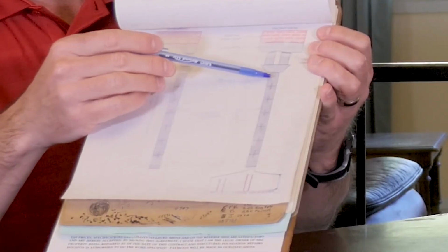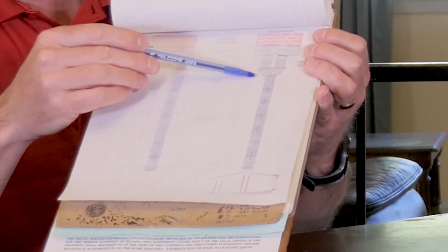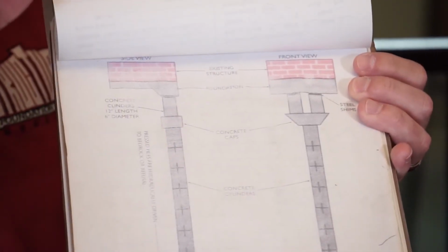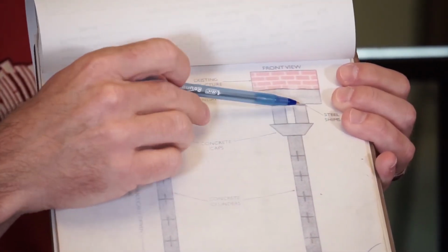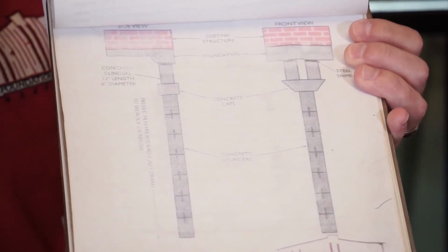Once they're done, what they can do, and I can show you an example here. This is a straight line of rebar that runs through the column of these pilings that construct our pier. We build it up to the house, put that cap on top. The cap's actually rectangular. That gives us a platform to lift off. They lift off that platform, and then they can put another piling on top of the cap and shim off the top of that using what are called shims, which are 4-inch by 4-inch, 1/4-inch thick steel plates. And then they can pull the hand jack out, put another piling in its place, and shim off the top of that, making it a tight fit with the house.